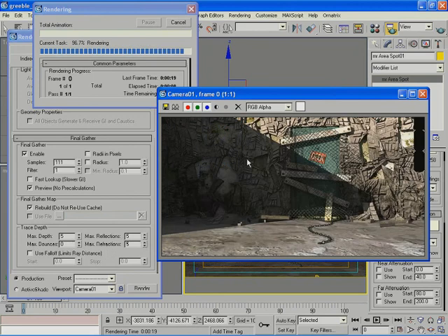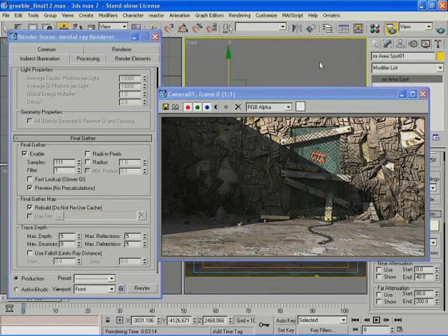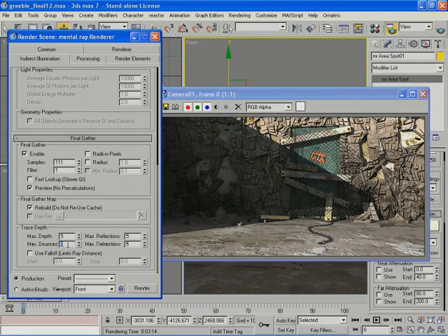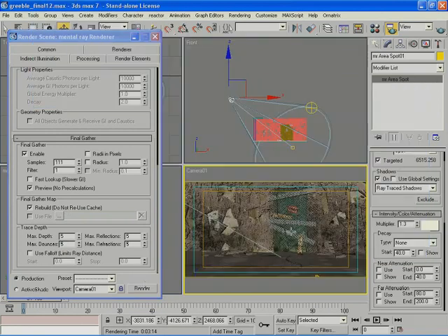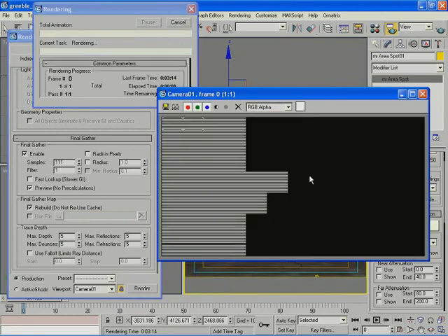Yeah, I need to lock the camera view so that I render from the camera view. Of course, when I increase the maximum bounces, it's going to take longer to render, but the result will be worth it. So now I don't have total darkness anymore, and I have really good shaded area in this part. Just looking at the pixels rendered so far, I see that it's no longer very dark. And this is because the photons are bouncing in and out over the walls in this area.